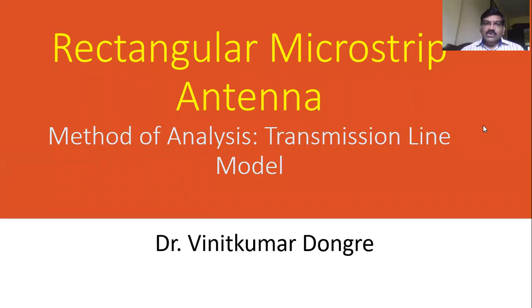Namaskar. So we are starting rectangular microstrip antenna. Now in the rectangular microstrip antenna, today we are going to discuss the design. And here the design is according to the method of analysis. So there are multiple methods of analysis. We are going to discuss the transmission line model. So this is what the transmission line model method is, and that is what we are going to discuss.